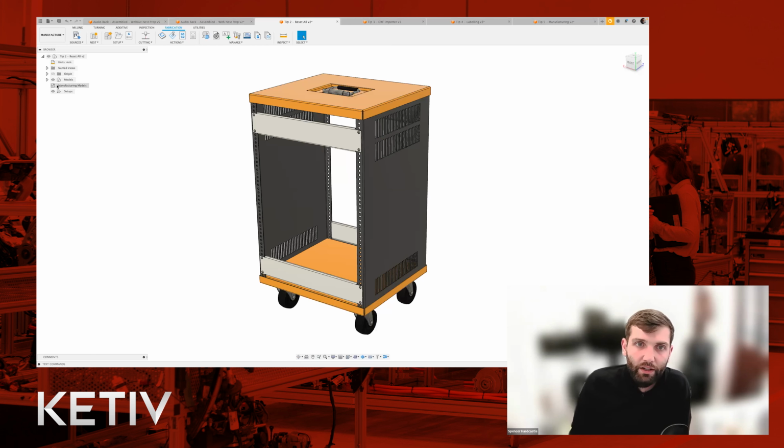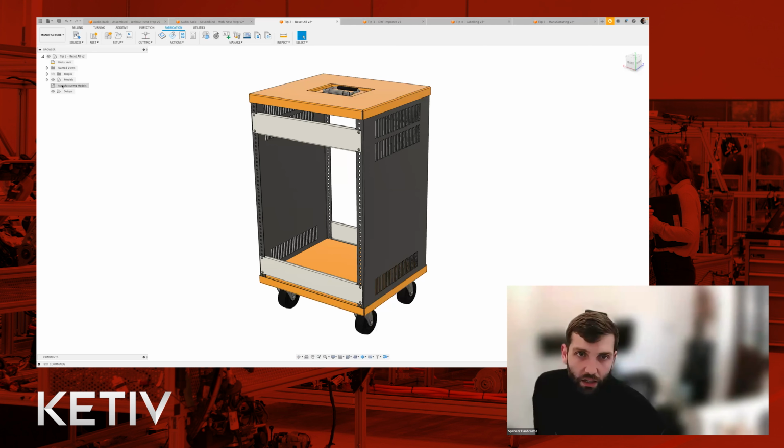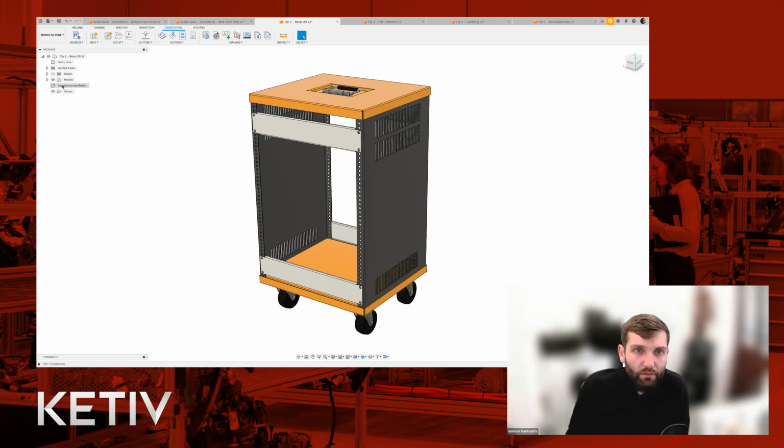Well, what you do is you head over to manufacturing models and you see there are no nests. There's nothing within the manufacturing models node now, but the node exists. And the node exists because you have created and calculated those flat patterns, those nestable shapes. And you did that when you opened the component sources or you opened the material library. So to reset all, to get back to the defaults, right-click on manufacturing models and press delete all.